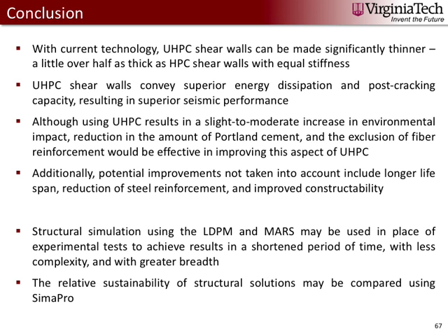Additionally to the sustainability results, potential improvements haven't been taken into account here, which include potential longer lifespan, reduction of steel reinforcement to improve constructability. In a more general sense, it's concluded that structural simulation using the LDPM and MARS can be used in place of experimental tests so that we can obtain results in a shorter time period with less complexity and with greater breadth of our study. And the relative sustainability of structural solutions can be compared using an LCA approach with the SimaPro software.